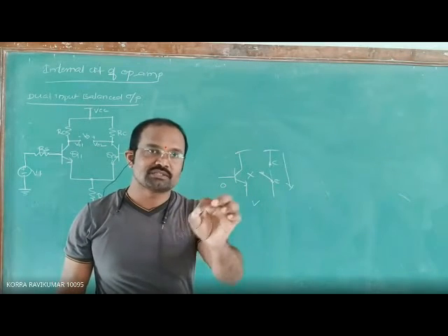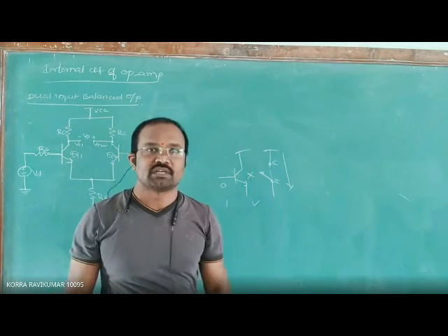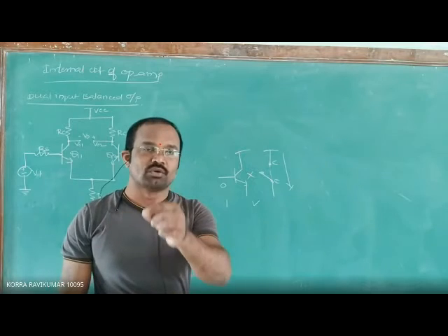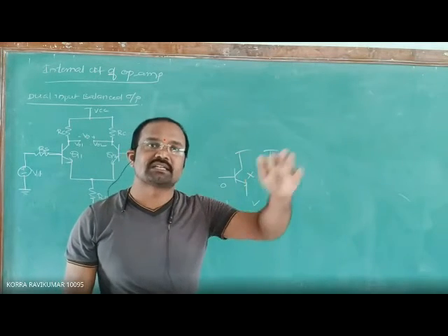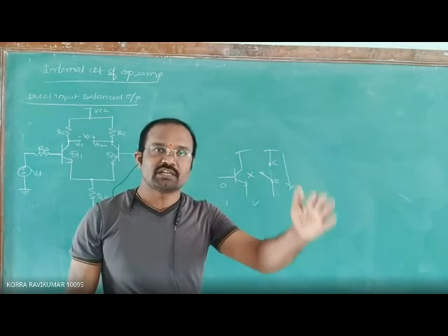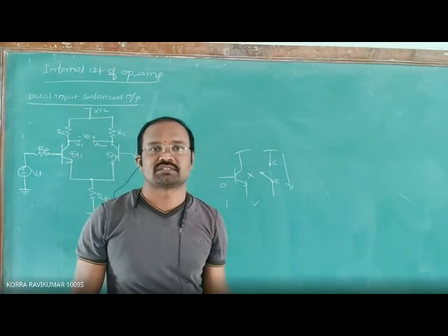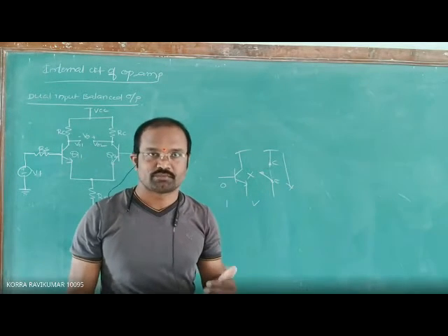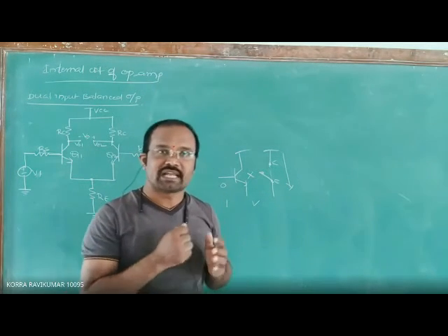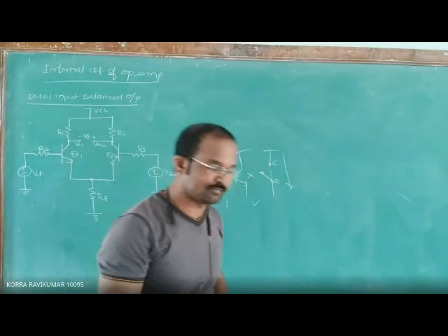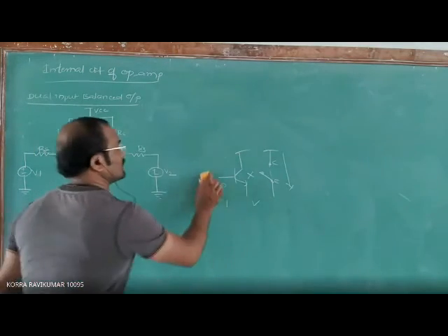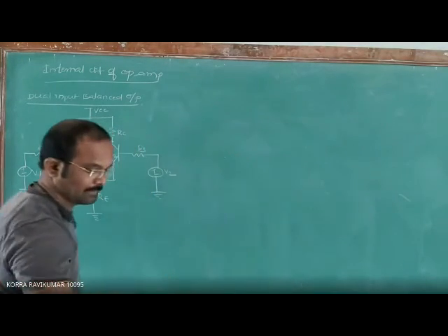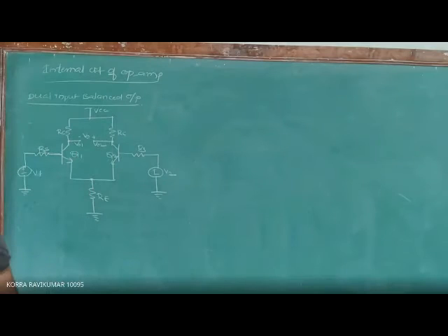If you apply 0 volts, the transistor remains in off stage. If you apply more than 0 volts, greater than the cut-in voltage, the transistor gets into on stage. In on stage, it acts like a short circuit, means on switch. That's why I'm telling you that the transistor acts as a switch. Because here we needed that. In case 1, let us take case 1.